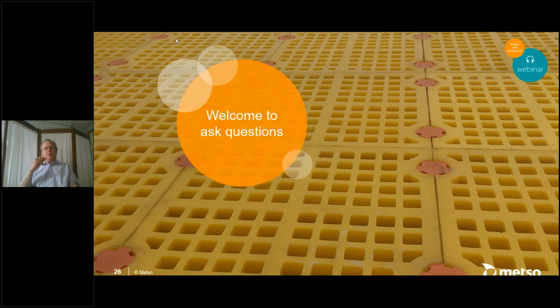And thereafter, you could say there are certain trends. Certain markets are more polyurethane than other markets, but polyurethane is also prevailing in the areas where you have really small apertures. It has always been easier to make really small apertures in polyurethane. So dewatering, drainage, and things like that are typical polyurethane applications. So that's, let's say, a short idea behind that.